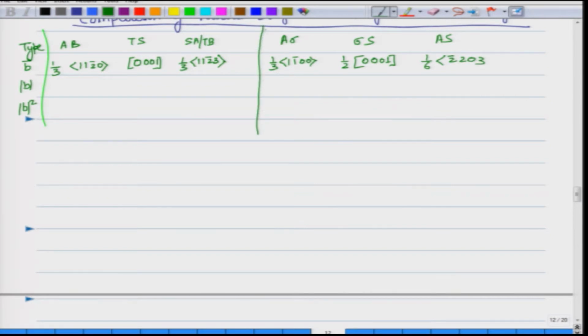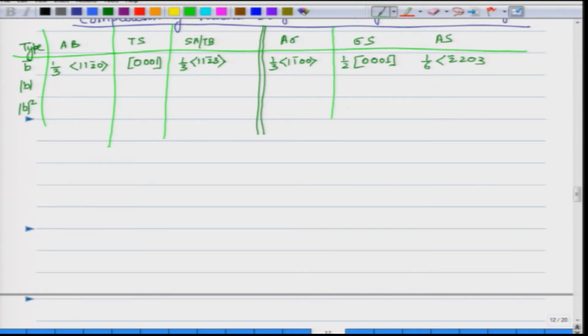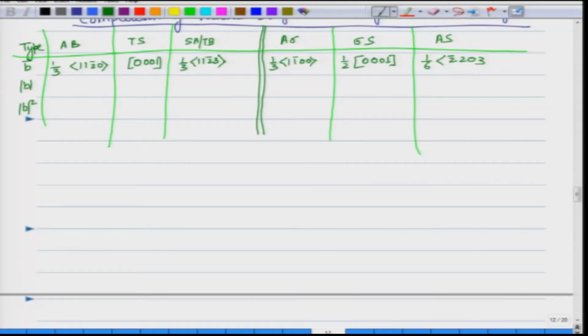So, these are the partials. On the left hand side we have the full dislocations. Now, as I have already given you the vectors, this is just the form of a vector, and like I said, from the bipyramid you would be able to directly get these vectors, and we have listed all the possible different perfect dislocations and partial dislocations.